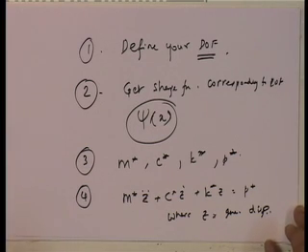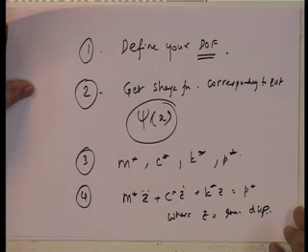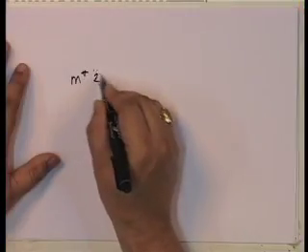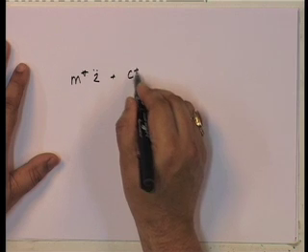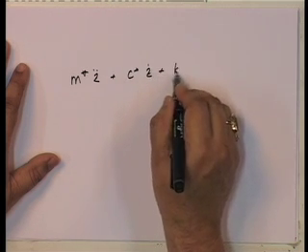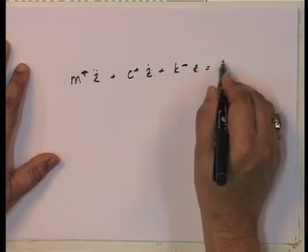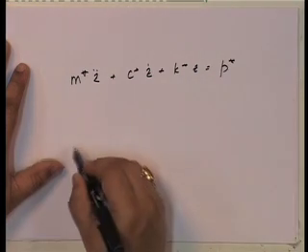Note that z can also be theta in a particular case, in which case m star, c star, k star and p star will be appropriate. Okay. So, once I have this, what happens? Well, I have m star z double dot plus c star z dot plus k star z equal to p star.